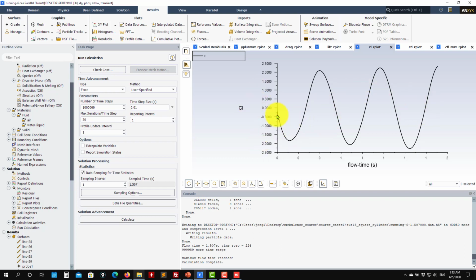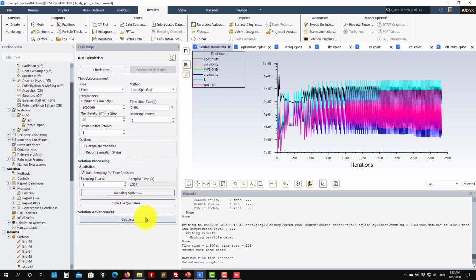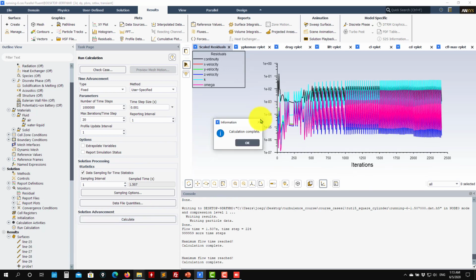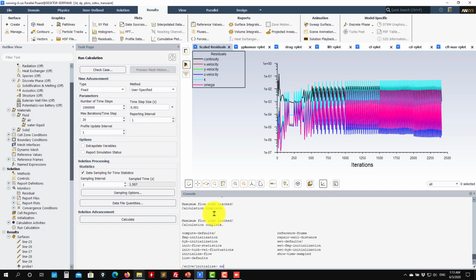That's why we run initially. We got an idea of time step, periods, and everything. So at this point we're running. I hope you get the idea. If I go here and reduce my time step, by reducing the time step I'm just improving the solution, but it will take longer. Just to make this concept clear, so let me put it here. I reached the time 1.5, so I just need to increase it here. Not full time, just put it back to 20.